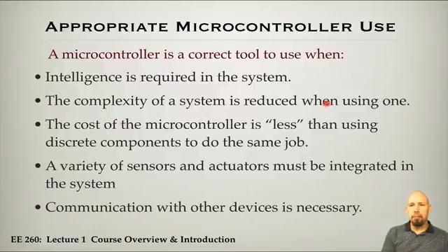The complexity of the system: you may have a system where the complexity is reduced by using a microcontroller. It turns out that you can set up that SOS kind of thing using switches, relays, and timers. But if you were to use all of those things, it can be a fairly complicated system by the time the whole thing is said and done. So if you can reduce the complexity, so instead of a bunch of relays, switches, and timers, you can do it more simply, in particular using a microcontroller, then it's good to do so.